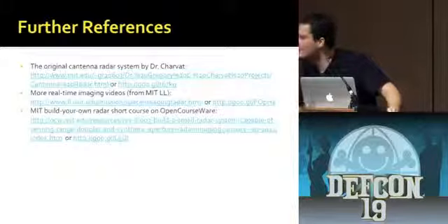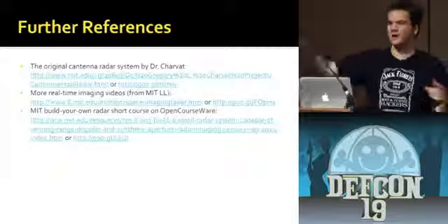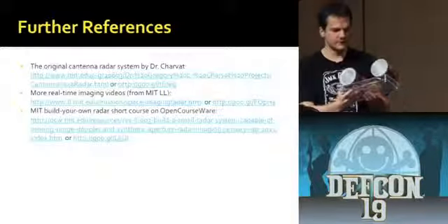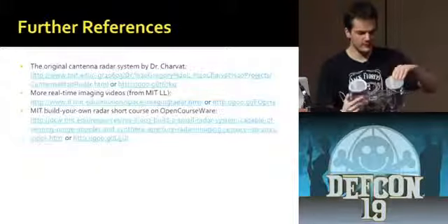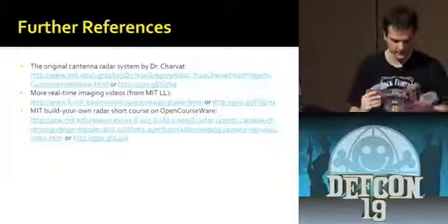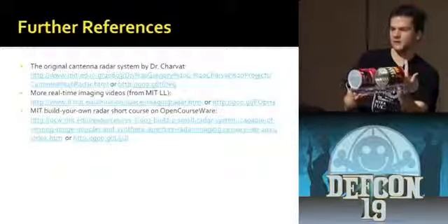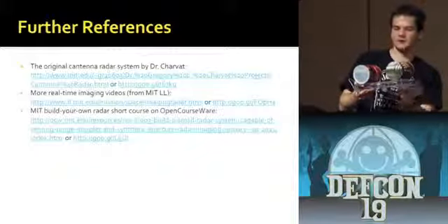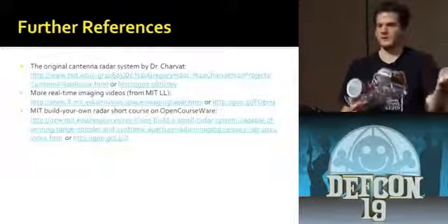Oh, well, the coffee cans are somewhat directional. Sorry, he asked why coffee cans as opposed to a different type of antenna. The coffee cans are fairly directional. They were really cheap because they're coffee cans and we had them anyway. But basically, it's going to be hard to see inside this thing, so you might just have to come back later and see. But the way this works is there's an SMA connector in here, and there's a little wire being fed into here. So this is basically a waveguide port. It's an adapter from that little feed antenna to this larger waveguide. And then it's basically a crappy directional antenna.